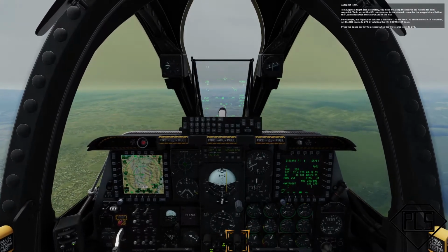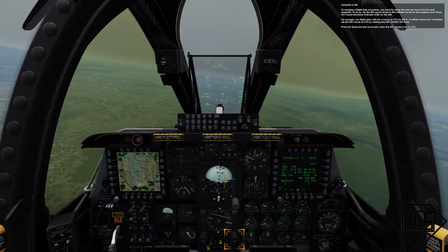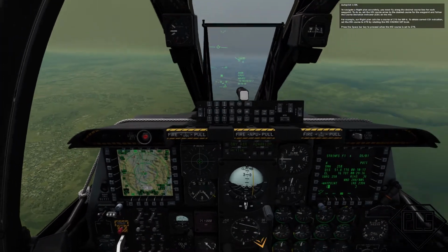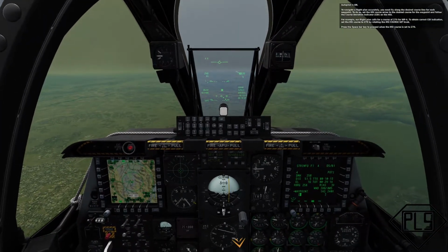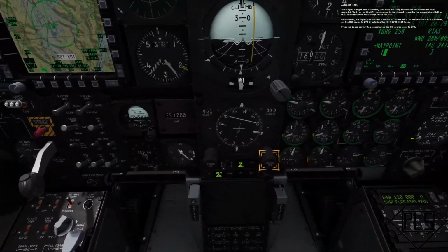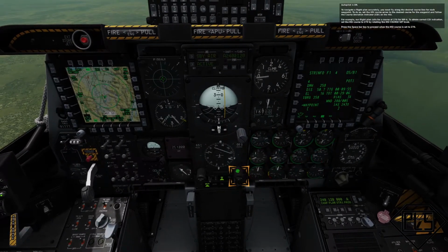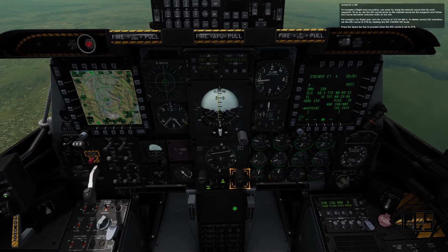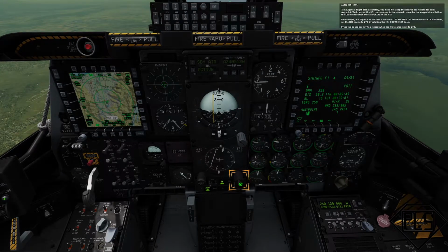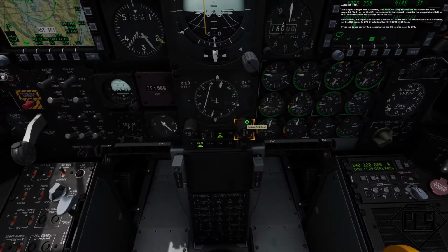Autopilot is on. To navigate a flight plan accurately, you need to fly along the desired course line for each waypoint. To do so, set the HSI course arrow to the desired course for the waypoint and follow the course deviation indicator, CDI, on the HSI. For example, our flight plan calls for a course of 270 for waypoint 4. To obtain correct CDI indication, set the HSI course to 270 by rotating the HSI course set knob. Press the spacebar key to proceed when the HSI course is set to 270.